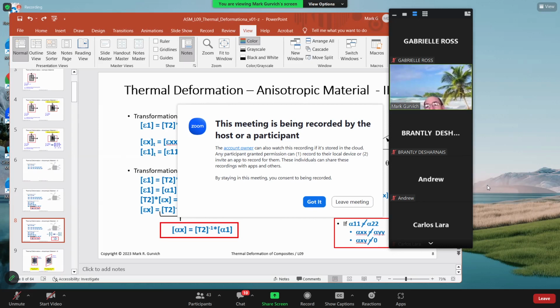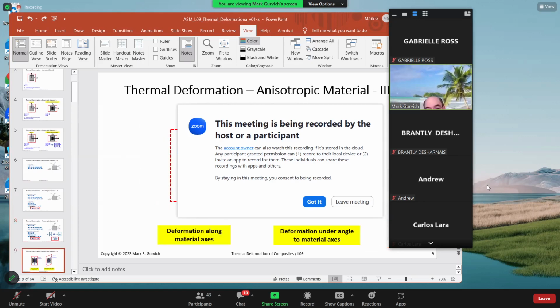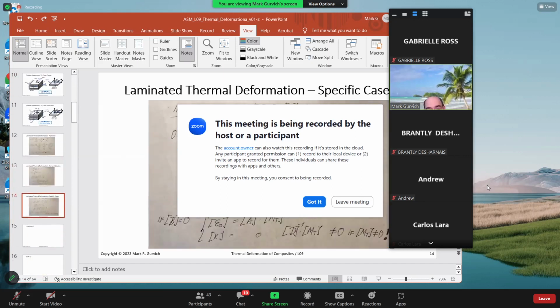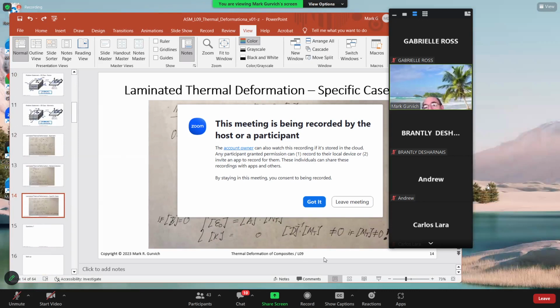So every time you see a material start to buckle, when originally it was flat, it's exactly this type of phenomenon we are talking about. And actually, it's a huge issue in the fabrication of composite parts. For example, if we are using thermosets, polymers like epoxy, you create a layup, put it in the oven and cure it under elevated temperature.